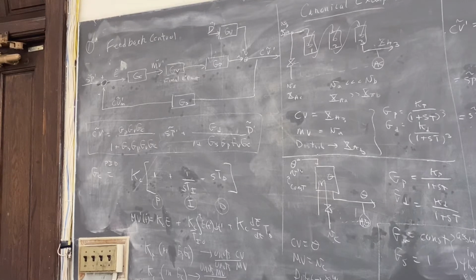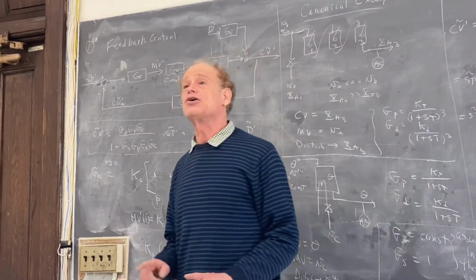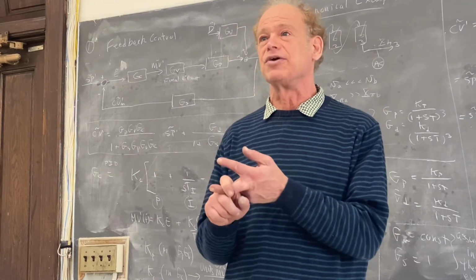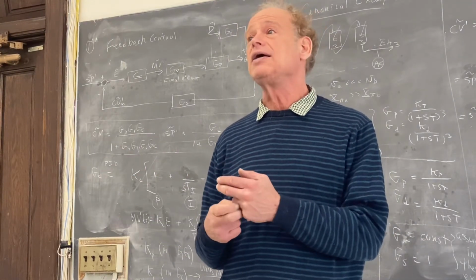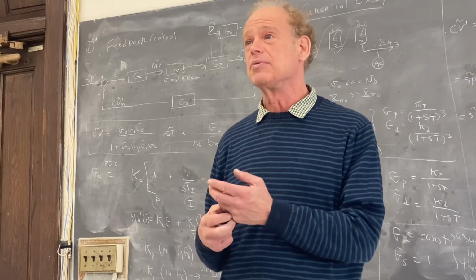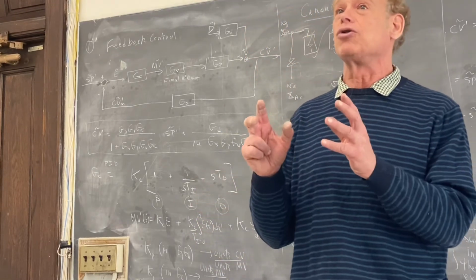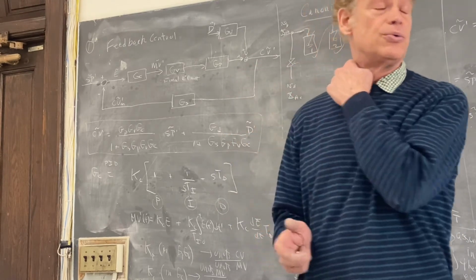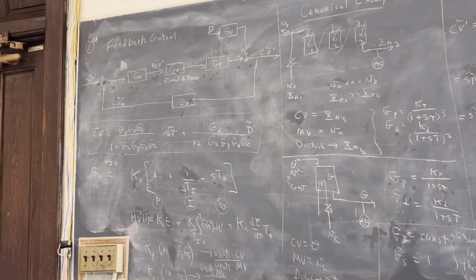Okay, so what else? There's a little bit of chit chat here, but as I said, the PID controller, what's good about it is it's easy to do the calculations. If you tune the parameters right, it does a very good job. And it's versatile. For many, many different systems, it does a very good job. But it's rarely the optimal. For a particular system, you could probably design a controller specially tailored to that particular system that will do better.